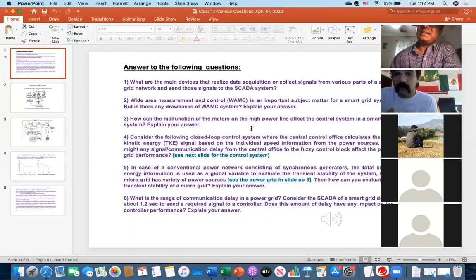Your voltmeter can measure for single phase 120 volt, for example, in this country, and for a three-phase system, line to line, it can measure 208 volt. So laboratory voltmeters or ammeters are rated only to measure voltage in the range of volts and current in the range of amperes, while on the high power lines, it is several thousand ampere, and as I told you, up to 1000 kV. So the only way to measure the high voltage and high current is with transformers.